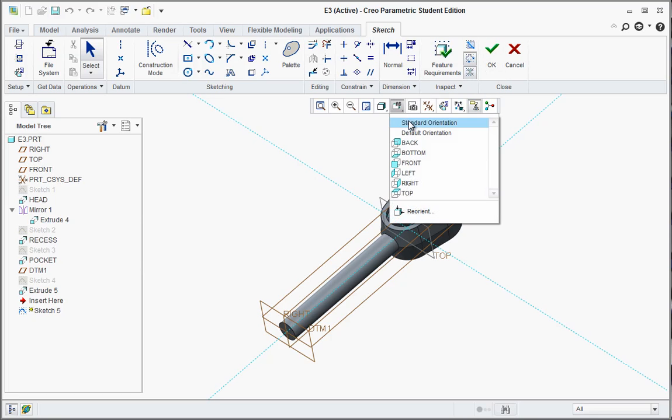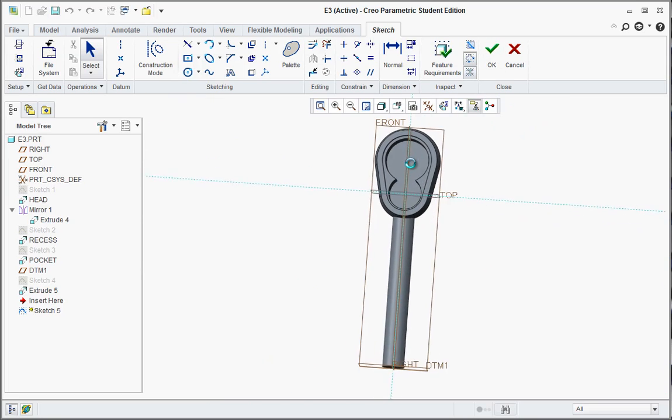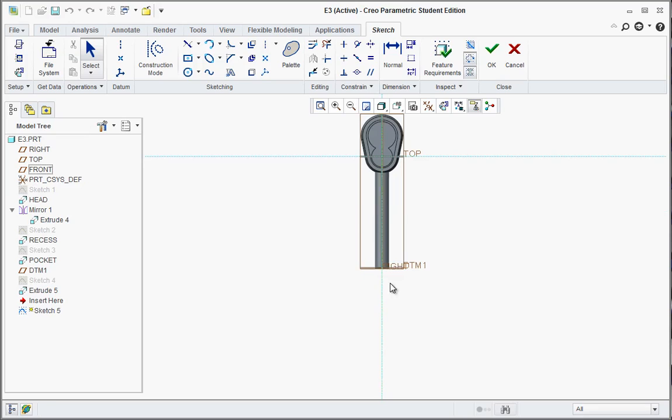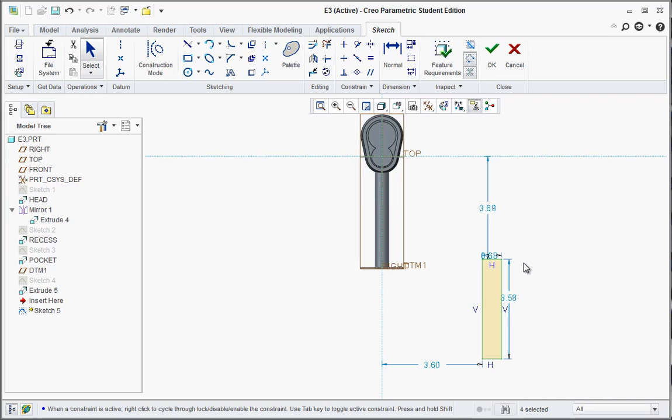Now go to the front view and zoom out a little bit, make some room for the handle to be drawn. The next item here, we're going to go ahead and take the corner rectangle, and off to the right here, draw what would look like the handle offset a little bit onto the right. Make sure there's no equal lengths. It should be vertical and horizontal only. Click, middle click a couple times.